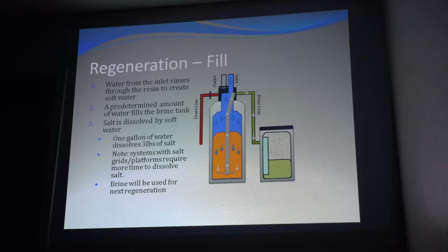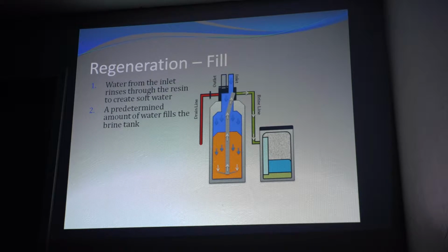Ultimately what it's showing is that your water comes in your inlet, your outlet is still closed, it comes up your distributor, but it diverts the water that would ultimately be for your outlet to your brine tank, giving you a soft water refill rather than a hard water refill. If you had a hard water refill, you run the potential of getting more buildup and hardness deposits in your brine tank.